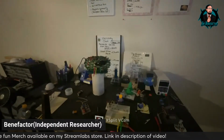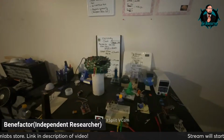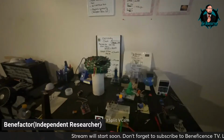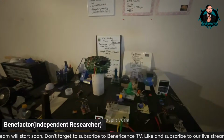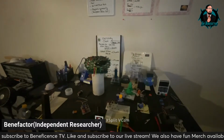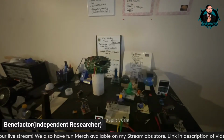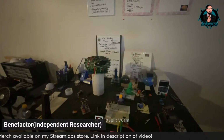And what we're going to be doing is adjusting the duty cycle. And we did this earlier on Mike Does' YouTube channel. He suggested that we kick it down to 5% high duty cycle. And it actually helped power the system at a lower input. So we were experiencing the same kind of power output with a tiny bit of a dip in the input amperage. So that might be something to look out for.